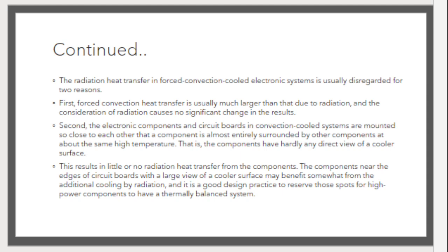The components near the edges of circuit boards with a large view of a cooler surface may benefit from some of the additional cooling by radiation, and it is a good design practice to reserve those spots for high power components to have a thermally balanced system.